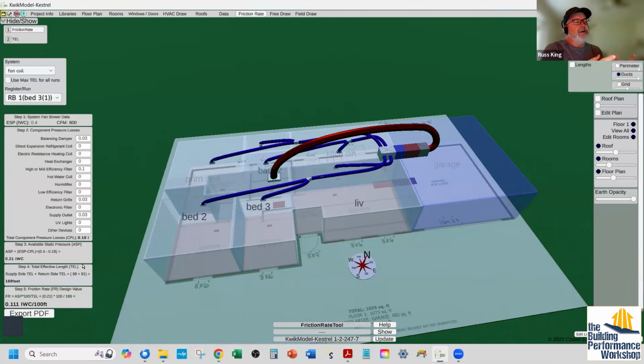If the difference between your best run and your worst run is not that big, it doesn't make any difference. But if you have a really short direct run and a really long run that goes to a bunch of fittings, and they both need 100 CFM, you want those to be two different size ducts. You don't want them to be the same size duct. And if you use one friction rate, they'll be the same size duct, and that's not correct. So it just kind of depends on the house too. And in that case, you'll end up using those dampers that you're building in on every run a lot more, because you'll be damping down all the short runs, which you shouldn't have to do on every project. Yeah, let the duct sizes do that for you.